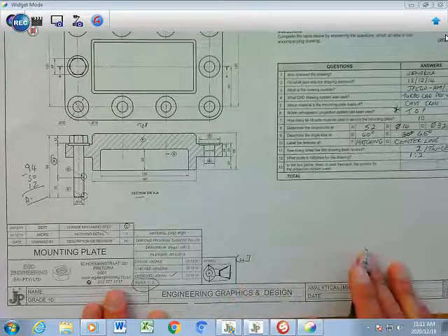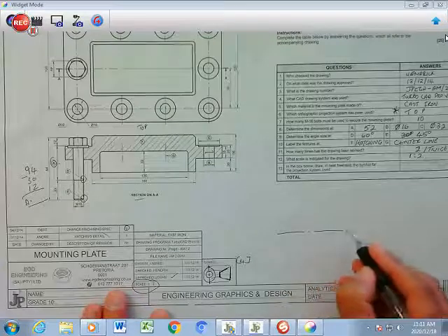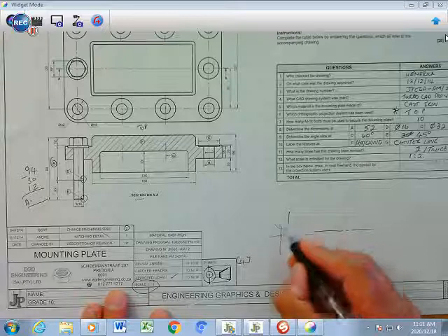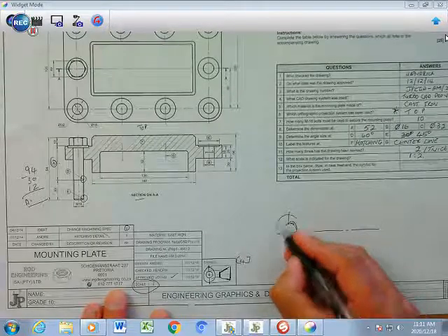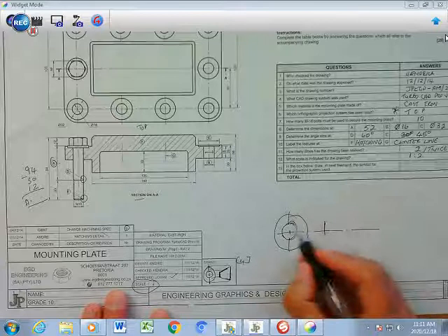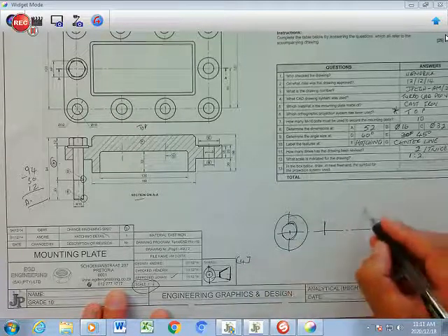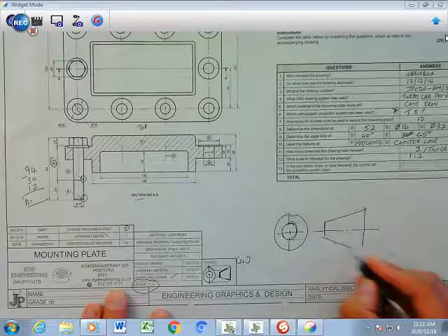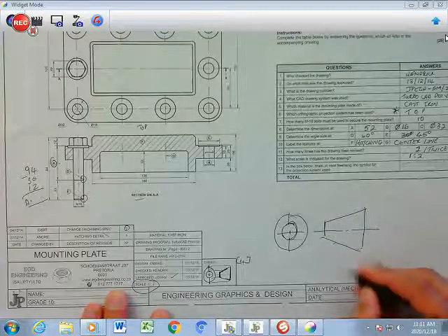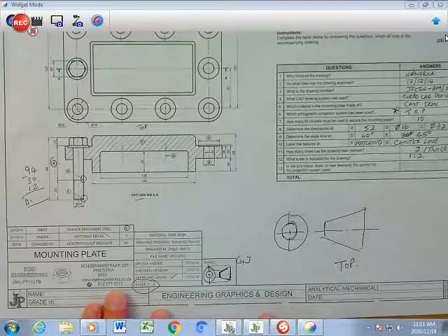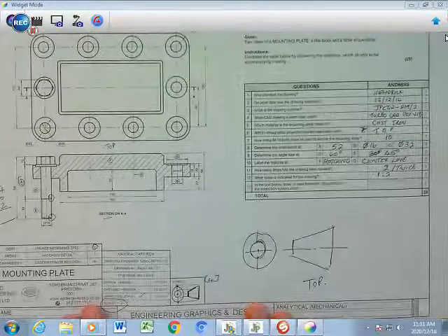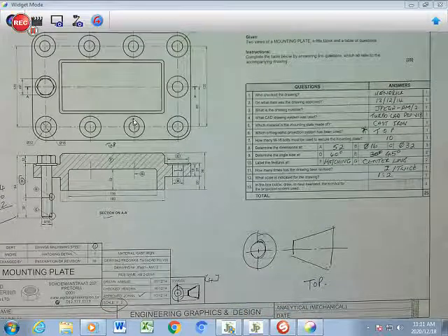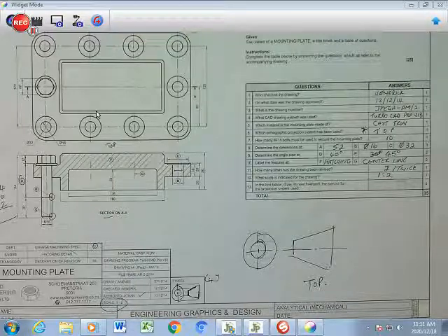I'm going to redo it quickly. They give you a center line. So you look at one of it, and you create another center line. You put in a small circle, put in a big circle, put in this line reflecting to that there, put in a longer line any distance away reflecting that there, and then you slant it like that. And that is your third angle orthographic projection symbol. Alright, I hope that's clear. That's a little bit of content information that we need for our mechanical drawings.